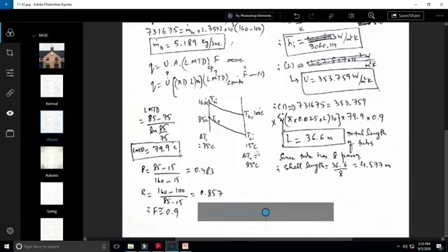And similarly delta T at section number 2 would be 100 minus 15, meaning 85 degrees Celsius. So now we will calculate LMTD, which would be (delta T1 minus delta T2) over log of (delta T1 over delta T2), or (delta T2 minus delta T1) over log of (delta T2 upon delta T1). So the numerator will be written in the same manner as the numerator has been written.